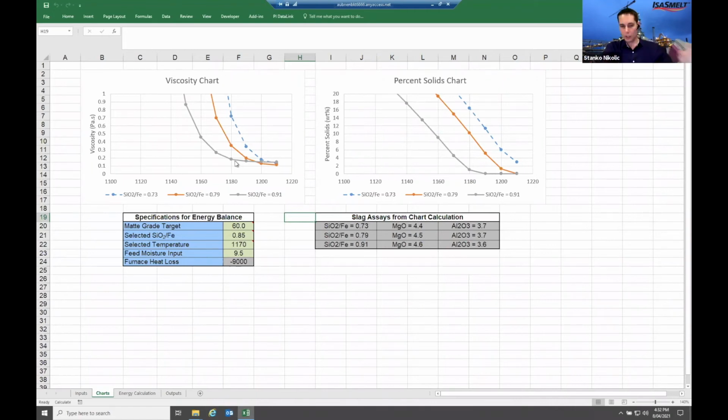When you look at other copper smelting technologies, they either have campaign lives of about 1 year or 2 years if they are just brick furnaces, or they have been extensively lined with copper elements, for example, the Mitsubishi and the Flash technologies. For them to be able to have a campaign life at all, they have to have extensive water-cooled copper elements throughout the whole furnace.